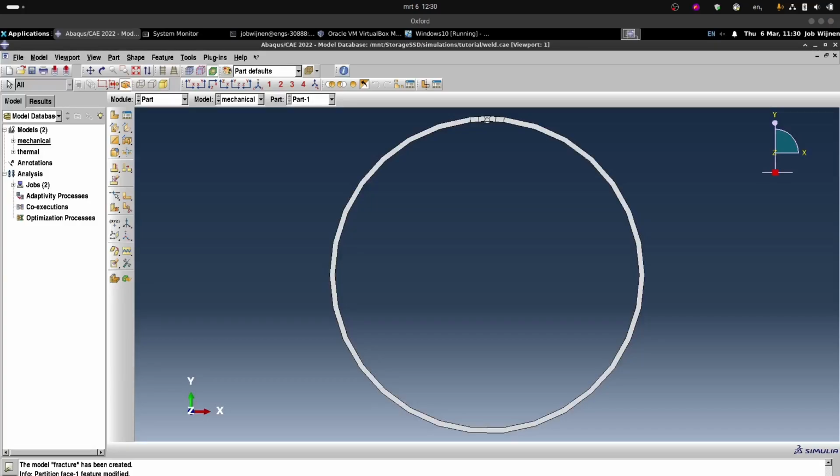In this video, I'm going to explain how to set up a phase field fracture simulation, so a failure analysis of a defect in a pipeline. This can be coupled to hydrogen diffusion and degradation, and the results of the welding model can be used as an initial input. To keep the same geometry, it's again easiest to just copy the previous model, and let's call it fracture.